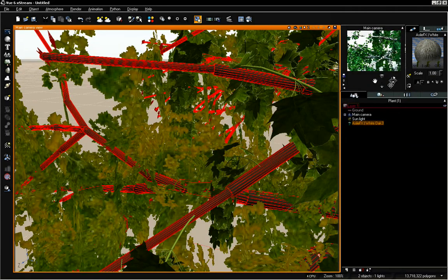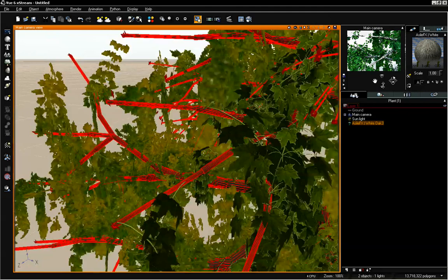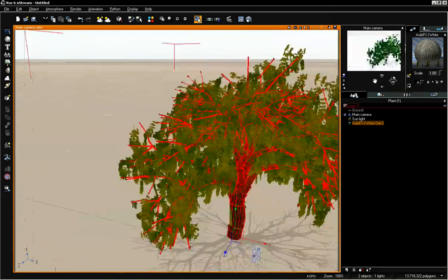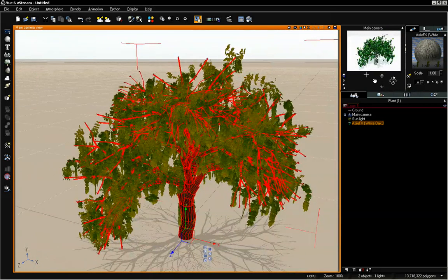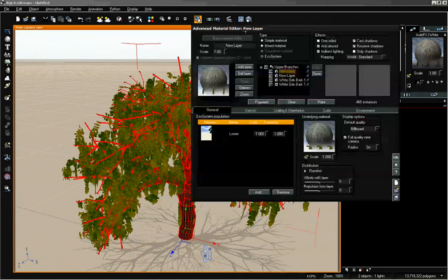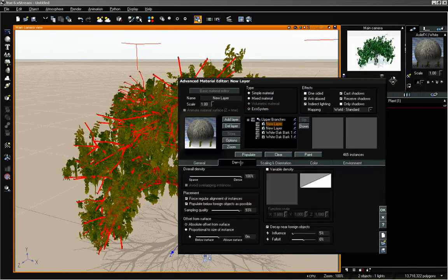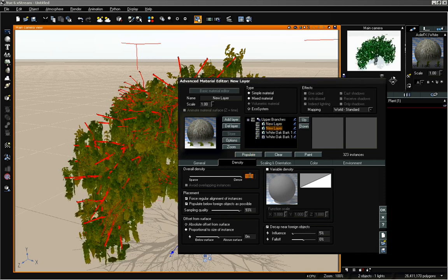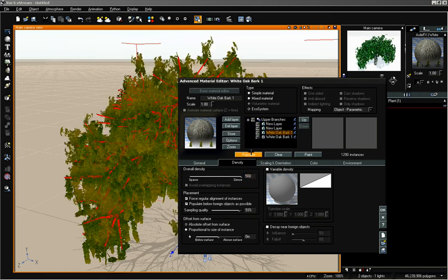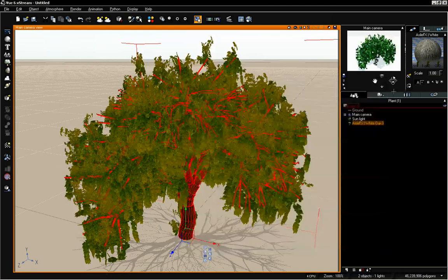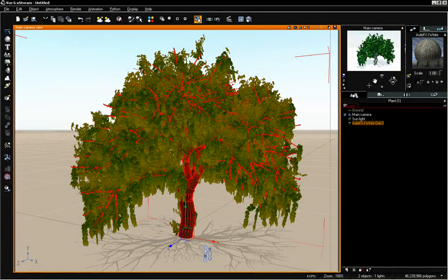And if you need to, you can increase the range of your radius from the camera. But since we're going to be increasing the density, it should show up alright where we're at right now with 3 meters. So we're going to select the density for each one of our options, and I'm going to go ahead and increase this up to 500%. Populate, go to our next layer, 500%, and then our top section, and repopulate. And now we have a really huge coverage of this tree.